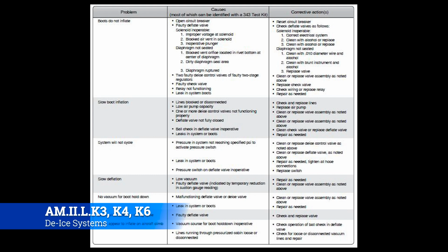A couple of things to remember whenever you're doing any kind of boot maintenance is you don't want to put anything on them that could potentially damage them in any way. You don't want to lay tools on them. You don't want to run hoses across them or anything like that. They are very, very sensitive to anything metal coming across them, and you don't want to have to replace or repair a de-icing boot.